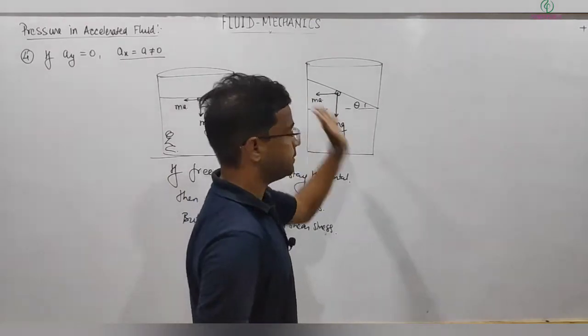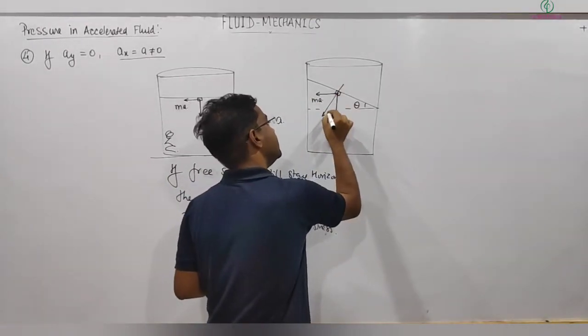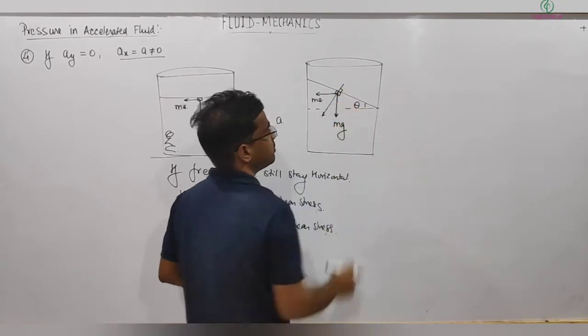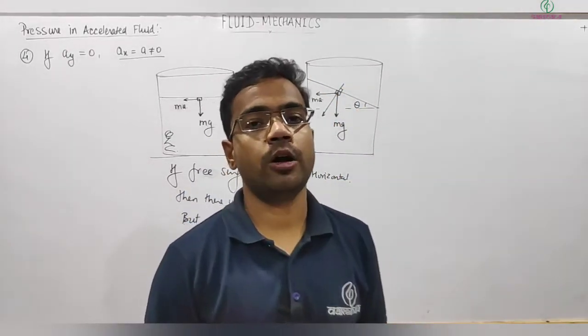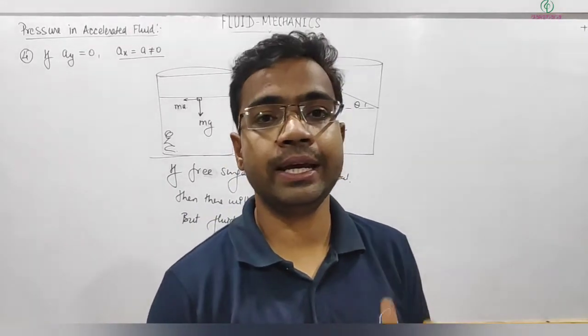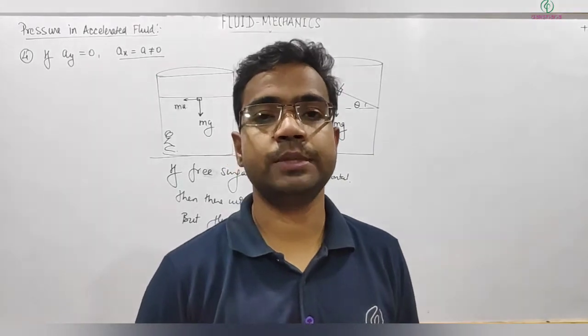The free surface will incline in a manner such that the net force is normal to this free surface, because normal stress fluid can bear, but it cannot bear any amount of shear stress.